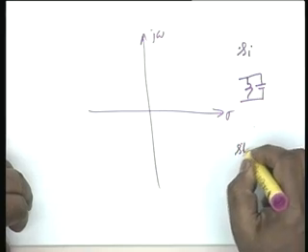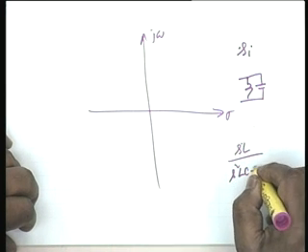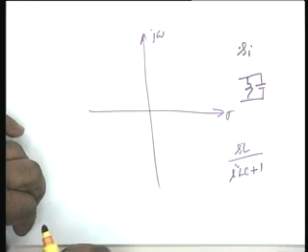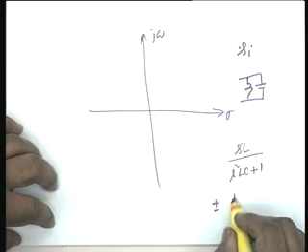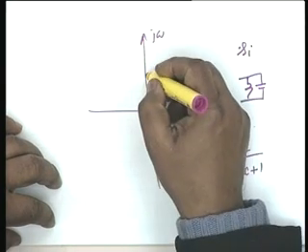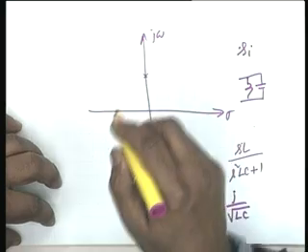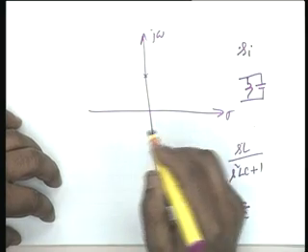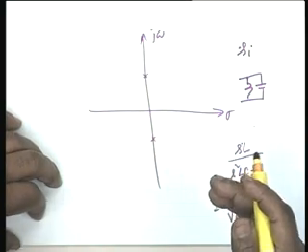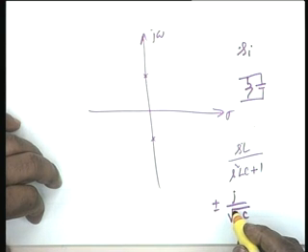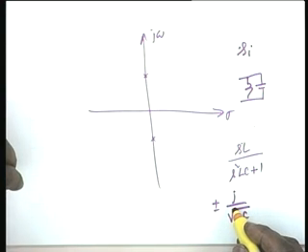For example, if you have, let us say, a parallel combination of L and C, the natural frequencies are on the j omega axis plus minus j 1 by root L C. What is the impedance? SL divided by S squared L C plus 1. So where are the poles? Poles are at plus minus j by square root L C. So you can have poles here on the j omega axis, alright, and the real part of this is 0. The real part has to be either 0 or negative.